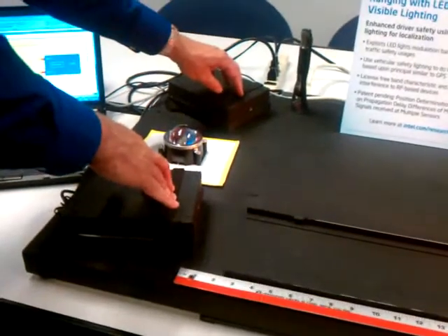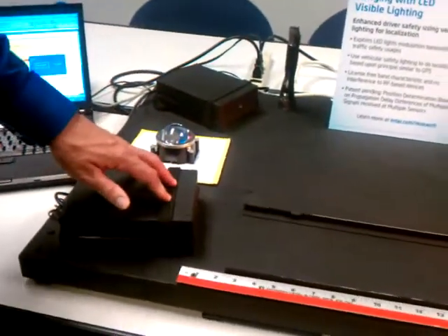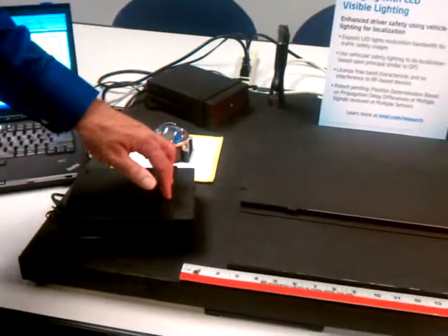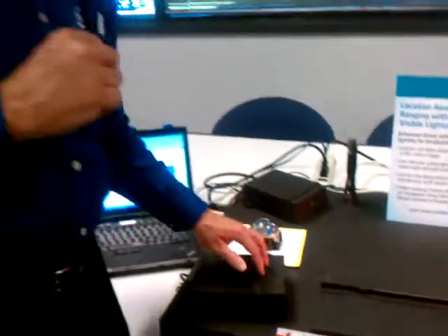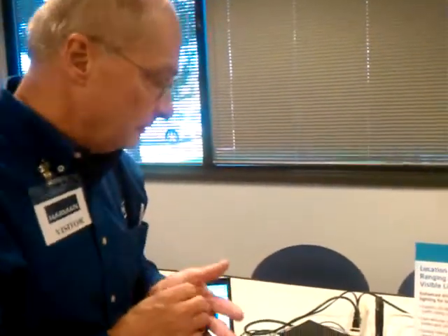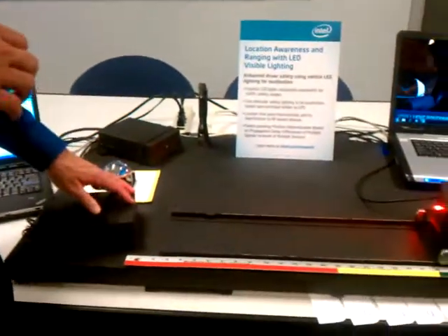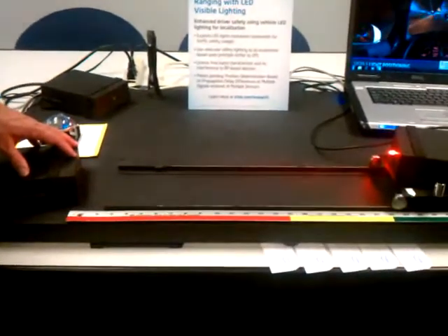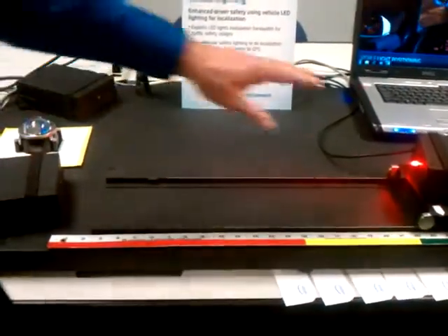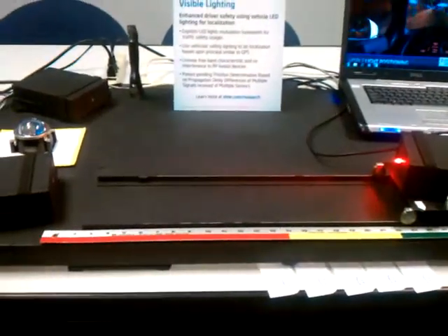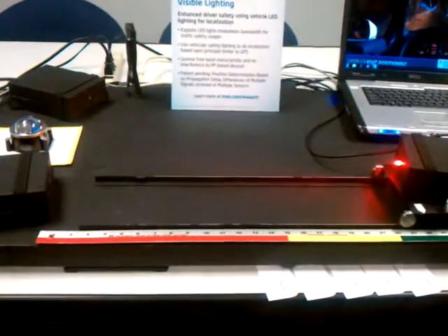That blinking light is observed on the photodetectors over here. And if I looked at the output of the photodetectors, what I actually would see is that 20 megahertz waveform. If I compared those two waveforms, I would see that they're slightly time skewed. There's a phase shift between the two waveforms. And by measuring that phase shift, we can translate that into time difference of arrival. And once we have that information, we can determine the position of this box based upon the geometry of the problem. Like echolocation, except for much higher frequency.